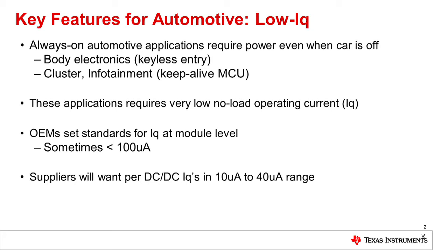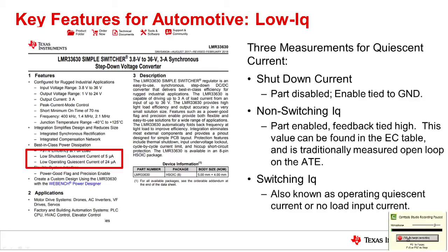However, even though this parameter is very important, it still can be confusing trying to decode the meaning of quiescent current within a datasheet because there are many different notations and many different types of quiescent current, and this can cause much confusion as to what is the true system quiescent current. Datasheet to datasheet, different types of IQ are highlighted on the front page or even throughout the datasheet, and this can lead to confusion when trying to decode what is the true IQ performance for your system.